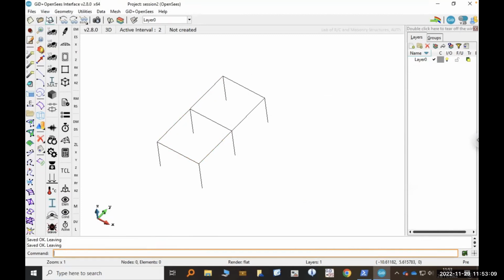You can do that. You have an automatic mesher that can create non-uniform meshes. Basically, GID has its own mesher that will mesh its geometric objects. And then because you specify OpenSees elements to your geometry, when that geometry is meshed, all the elements are the corresponding OpenSees elements. So if you want to do more sophisticated meshing, you can do that from GID directly.